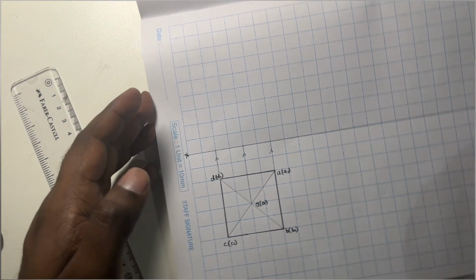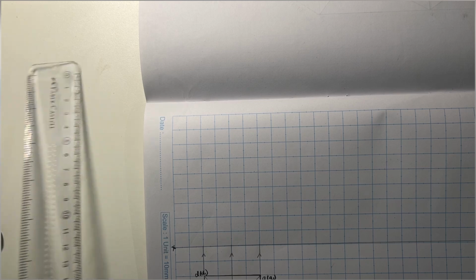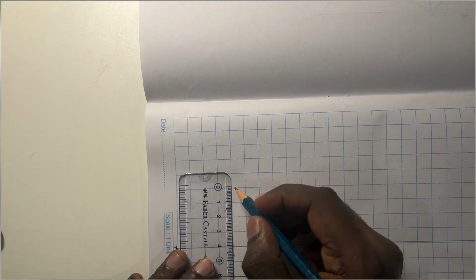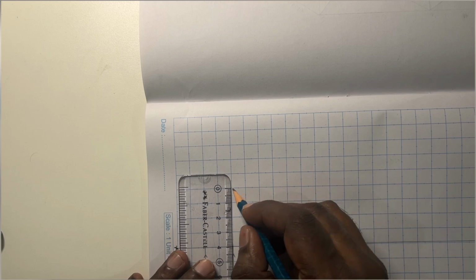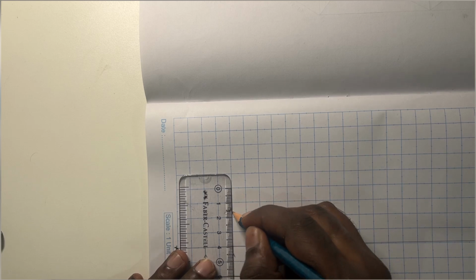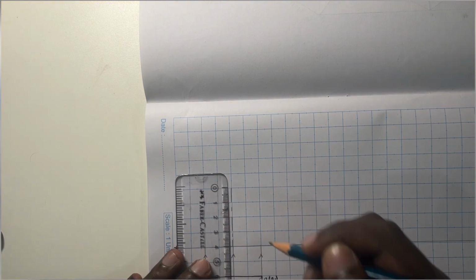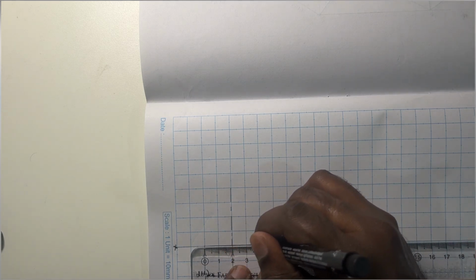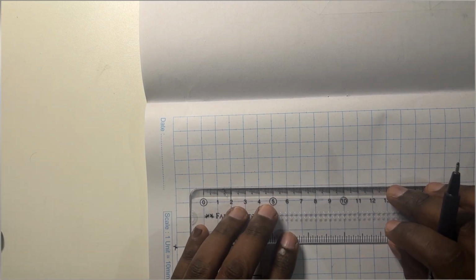So now let us draft the front view of this cube. The axis will also measure 40 mm since it is a cube. So let me draw the axis line again, which is a thin line, and then complete the front view by joining the end points of the projections. So this is the base of the cube and this is the top face of the cube.